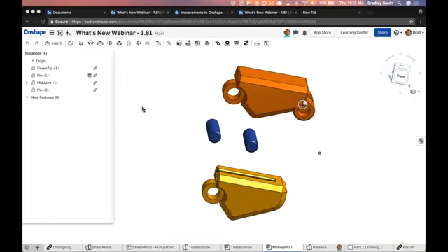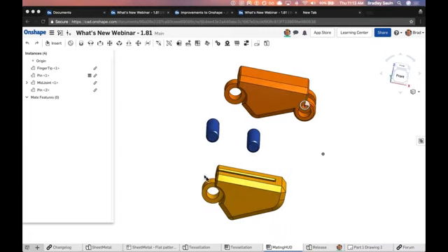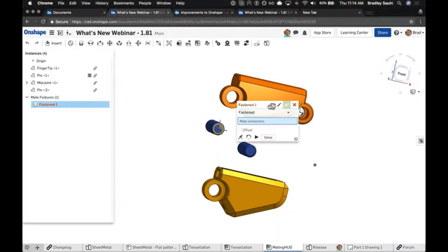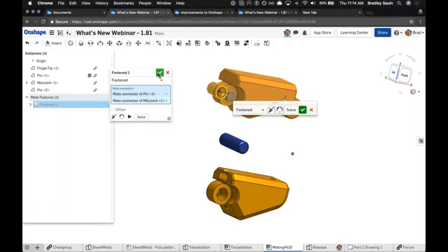So the next step here is getting into the mating side of things and our mating head-up display toolbar that appears. At least for me personally, as I'm working in Onshape, I like to do all of my mates all at once, whether it's on a sub-assembly level or on the top level assembly side of things. And in the past, when I had to perform a mate command, I have to come in here. I want to add a fasten mate to these two parts. Click the checkbox, or my mouse is over here editing the parts. I want to go and flip around the directions.